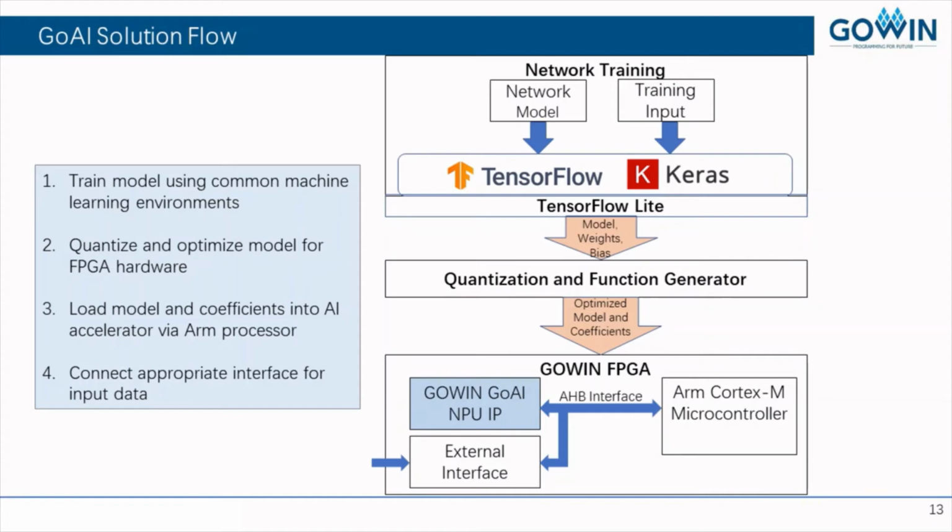But the deployment for the FPGA is really done in pretty much one setup. You just set up a batch file for the paths of all the software that we discussed earlier, the Gowin EDA tool, Keil, and I think there's a path for the TF-Lite file. And then you run that batch file, and it goes through and generates the C code and microcontroller firmware.